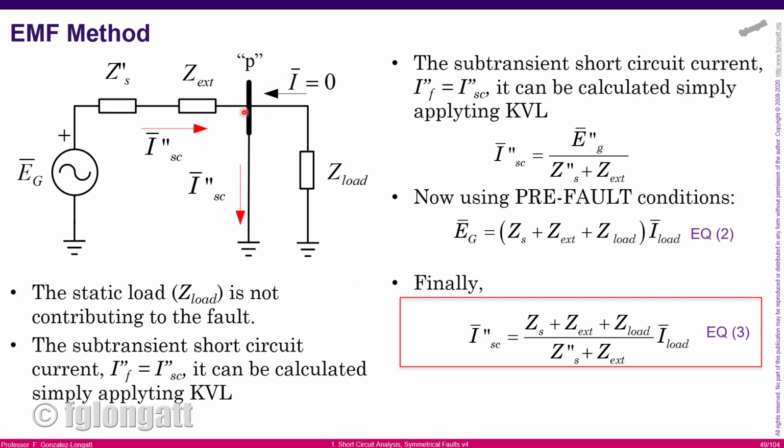If the voltage in this terminal is 0, that means the voltage across this static load is 0, the load contribution is 0, okay? What I'm trying to say is if we have a short circuit, and the load is an impedance, of course, the voltage across the terminal is 0, and there is no short circuit contribution to the fault, okay? However, on the left-hand side, the full current contribution is coming from this side, coming from the internal voltage inside the machine, okay?